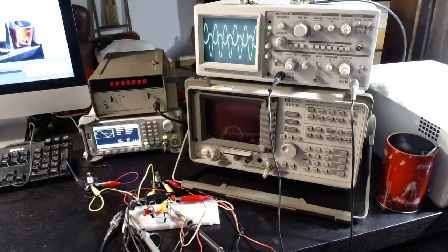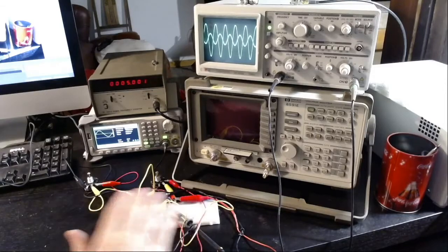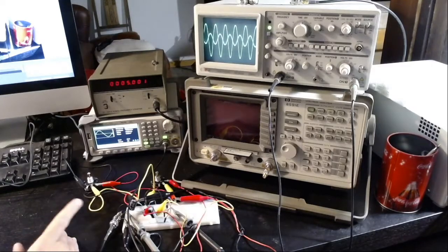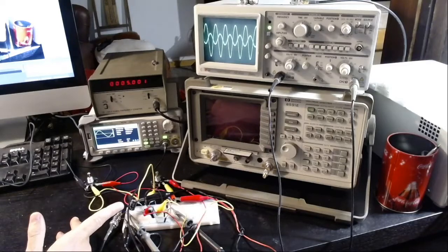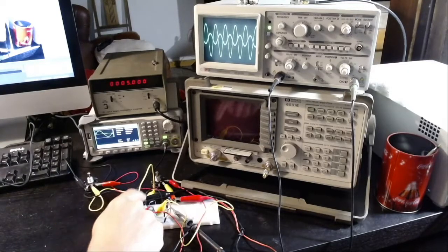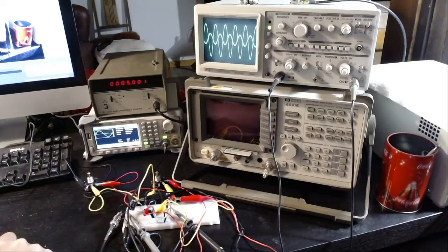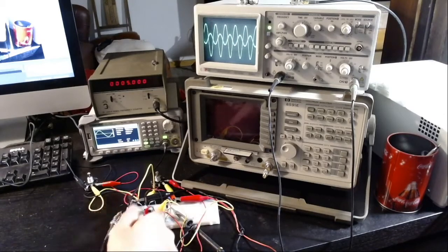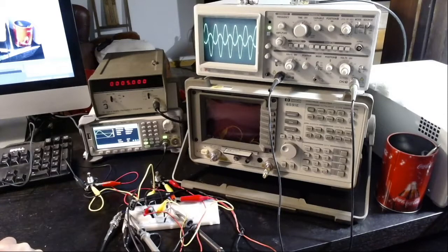And to design this amplifier, the design is very well known and is basically called the common emitter and common collector amplifiers together. There are two transistors here. So it's absolutely well known, but to experiment with the precise values of the capacitor, the resistors, and these kind of things, I used a software which is called LTSpice, and this has been very useful for me.